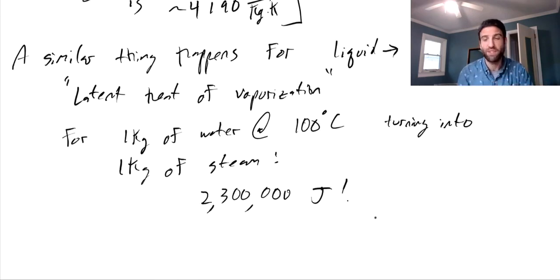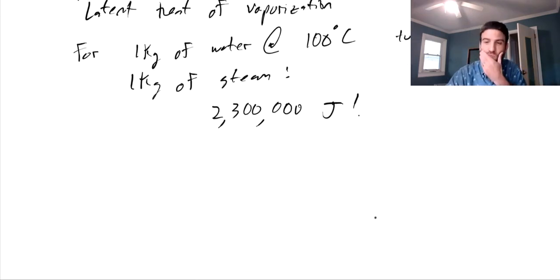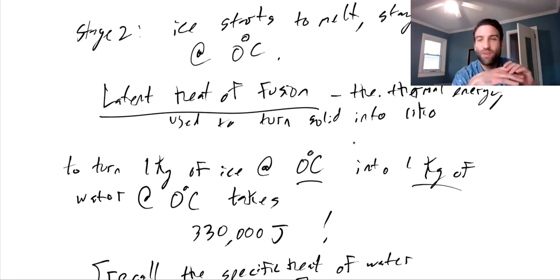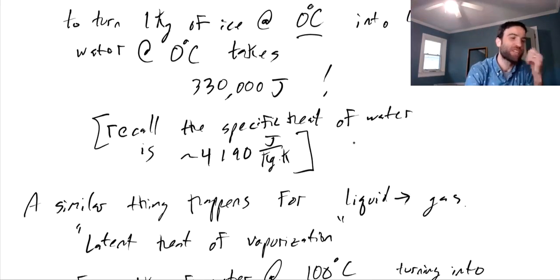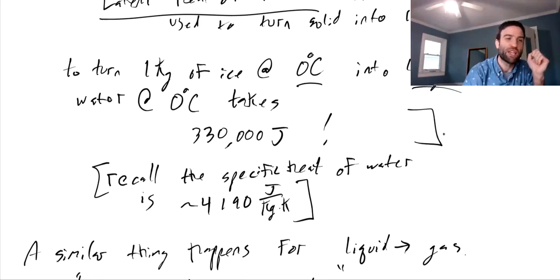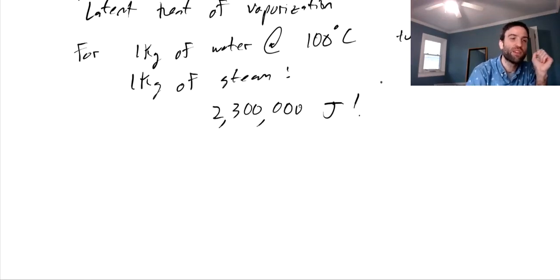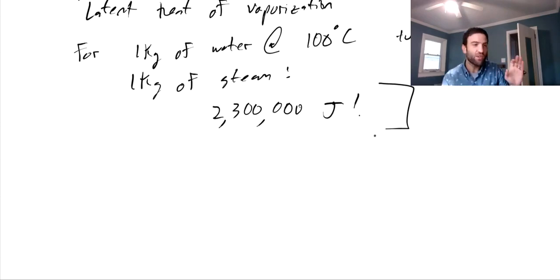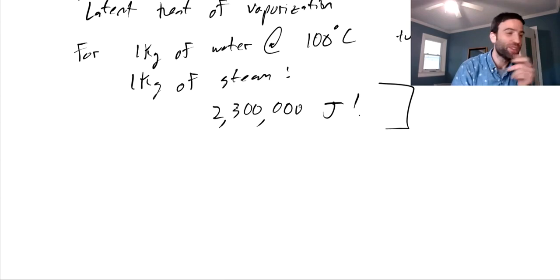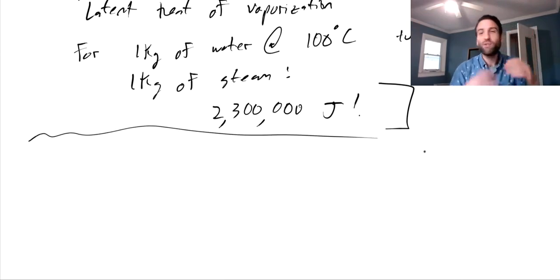And similarly for turning steam into water. Okay. Now, one of the reasons that I wanted to take a detour and talk about this is to emphasize these kind of large thermal energies that can be associated with phase transitions. Not associated with changing the temperature of something, but just with getting a substance to change from a liquid to a gas, or from a gas to a liquid, or from a liquid to a solid, so on and so forth. And that principle is actually how refrigerators work.